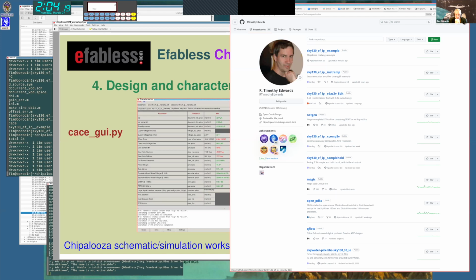And while co-simulation right now works when you have a Spice file and you want to simulate some Verilog block as part of that, it's not set up to simulate a giant Verilog block with some little Spice block inside it, which is actually what you want. If you have your analog IP and the rest of the system is this big digital system, then you'd really like to just simulate that little block in Spice and the rest in Verilog. Because that doesn't work, my favorite method is just to create a little Verilog wrapper for the analog block.